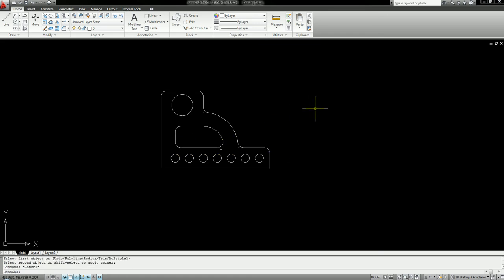And this is exercise 2-20. Again, we just did the layout. We used the fillet to get this radius right here, offset to get in here, offset to get the backside, and then we used fillet to round off all our corners, and we used a rectangular array to get the pattern that we have down here.